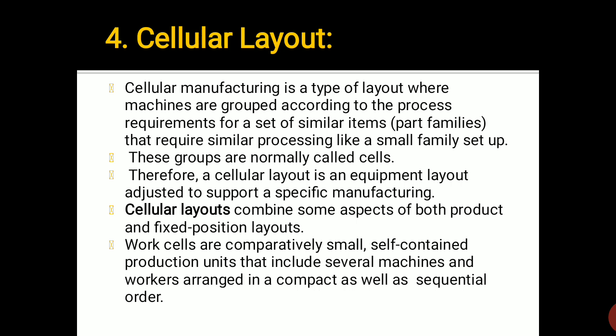That means cellular layout is such an arrangement in which the equipment is wisely adjusted for specific manufacturing. Next, cellular layout combines both aspects of the product layout as well as the fixed position layout. Whatever the advantage of the product layout was, we can fix it here, and it is very much possible.